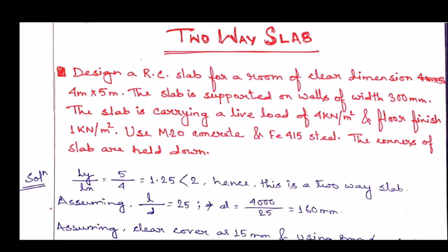and for both sides, that means for longer span and shorter span, we have to design reinforcement for middle strip only, and for 4 edges we have to provide edge strip as per IS 456-2000. The total consideration of two-way slab is given in Annex D of IS 456-2000.